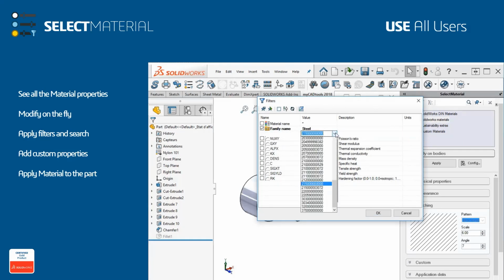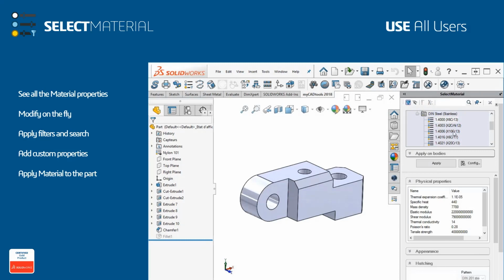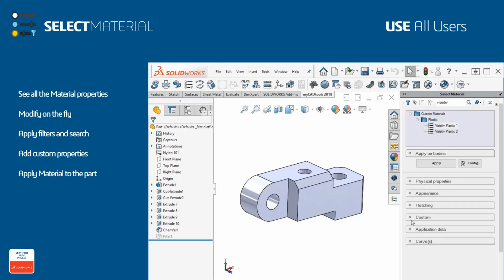For example, let's look for a material with a Young's modulus above 215 gigapascal. Then just click Search for the filtered list. Custom properties can be added to the materials and they will be transferred over to the part. This tool can make it much easier to filter and customize the default materials, allowing for quicker material selection.